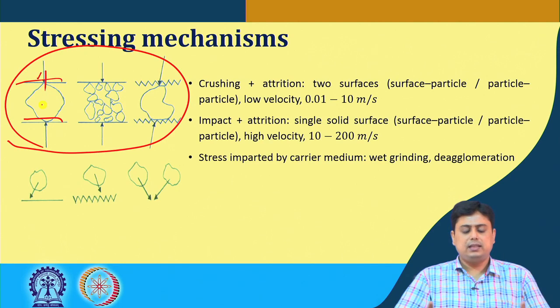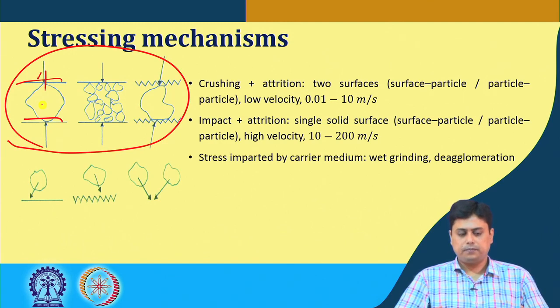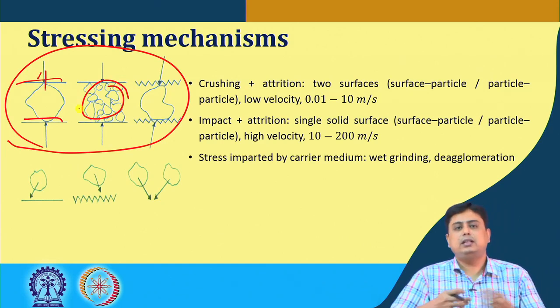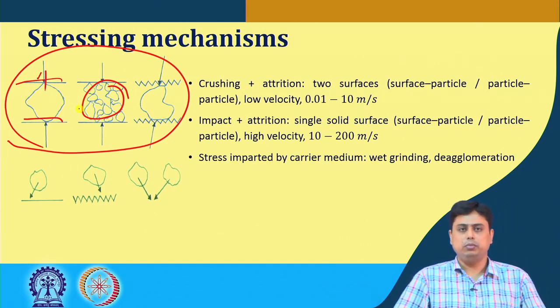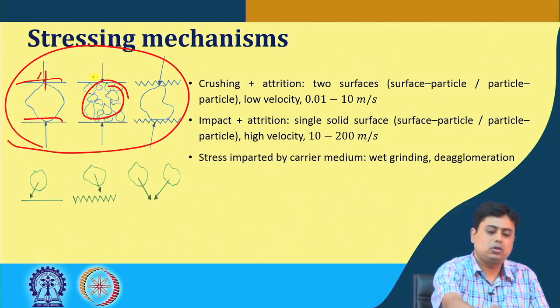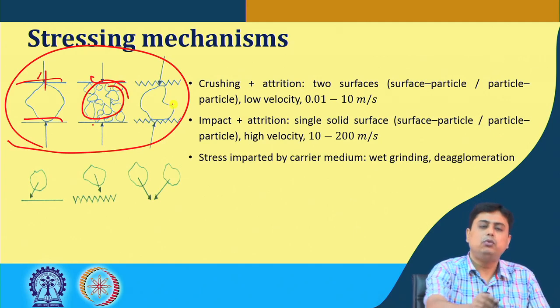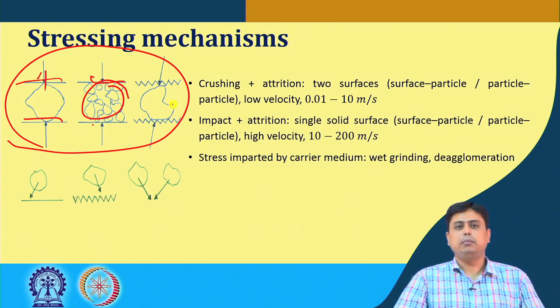In this case, if this is a lump or a block of solid, it is just crushing. If there are stacks of solid particles, here crushing plus attrition, that is in between particles, also comes into play. Instead of solid surfaces that crush from both sides, it can be some fluidic media with a high impact that can also crush these particles.